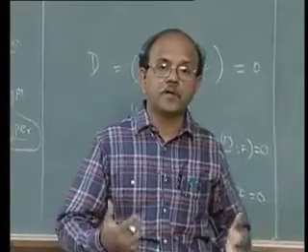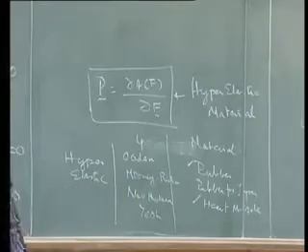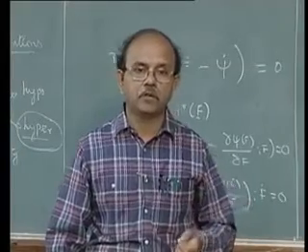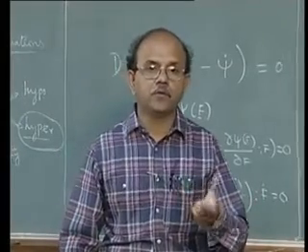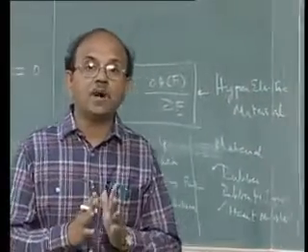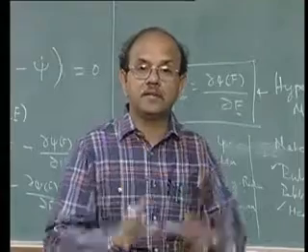For example, in Abaqus you will have the Ogden material, the Yeoh material, the Mooney-Rivlin material, and so on. So when you want to analyze, say, a tire, the first thing to do is ask: what is the appropriate representation model for the tire rubber?